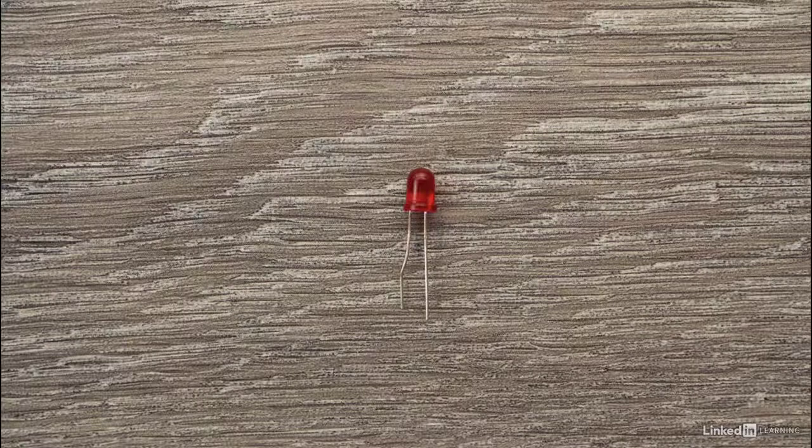Start with the one color LED. It has 2 leads, one that's longer than the other. The short leg is the cathode. That side will connect to the ground. Connect the other side to the 270 ohm resistor, then to GPIO 14 as shown in the handout.